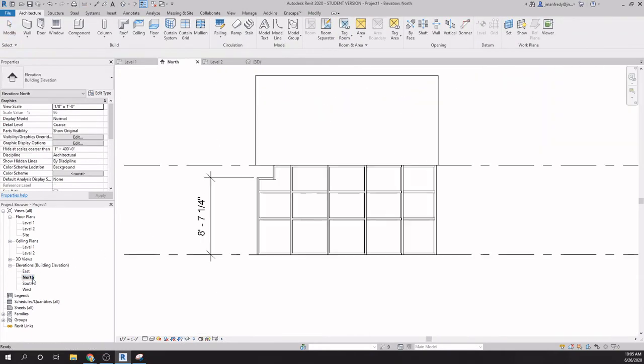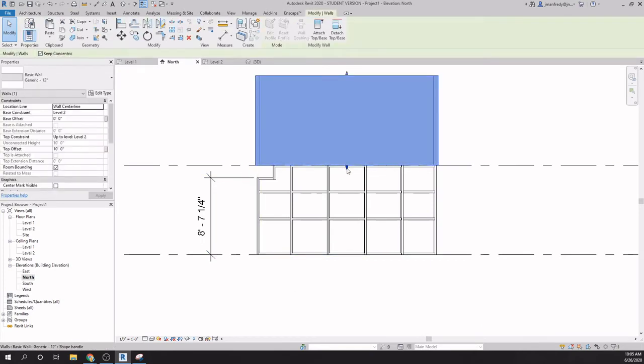So from the front elevation, this is going to get pulled down lower than it. And it seems here that it doesn't like the lowering of the curved wall below its level. For example, here, it's on level 2, and it doesn't let me move the base or the bottom of the wall lower than its current location. And that might be a bug, an oversight. Hit apply, and yet again, this should have been 2 feet below the second floor, and yet I see nothing here.